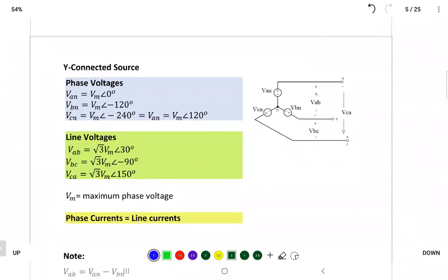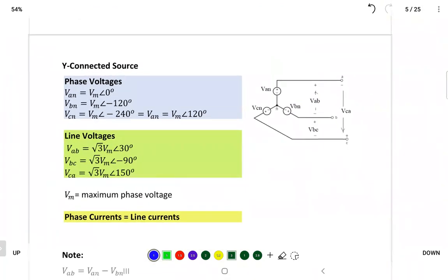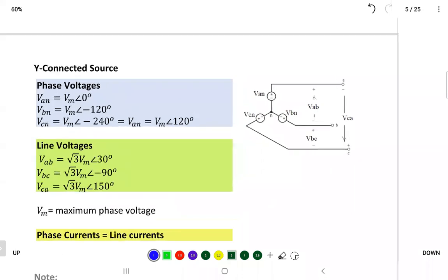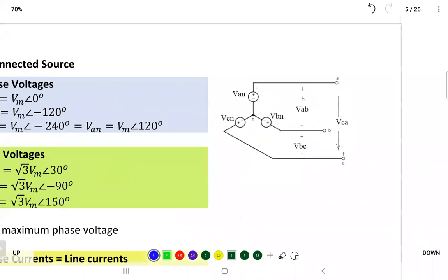Well, now let's see how we can connect the three-phase. You can connect three-phase in different ways. You can connect as a star, sometimes called star connection, or Y connection. It's the same thing. How do you do that? That's the source. You have A dash, B dash, and C dash. The ends of the coils you connect together in one node and call it N, neutral. That's how you do a star.